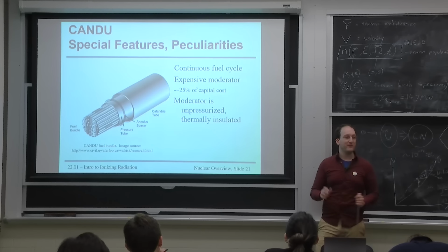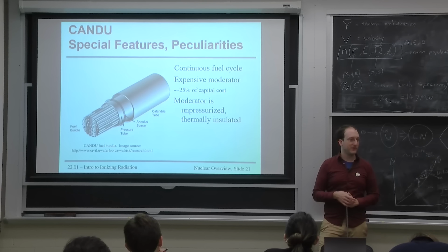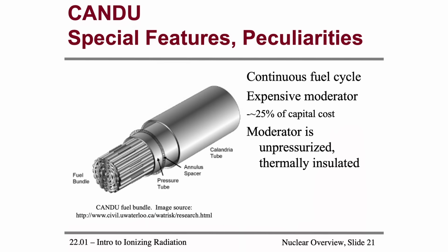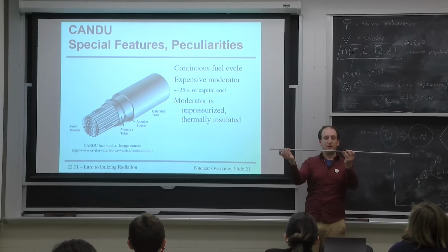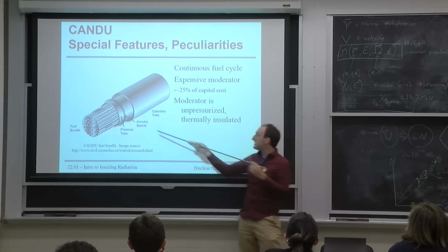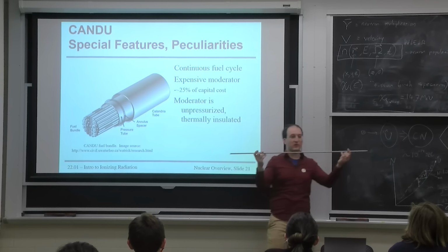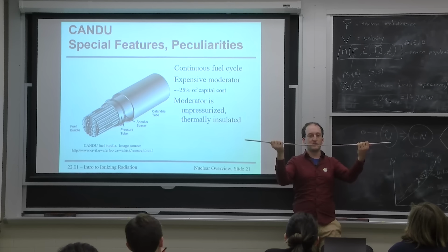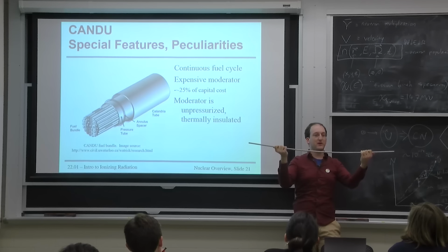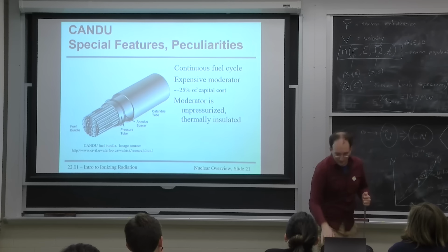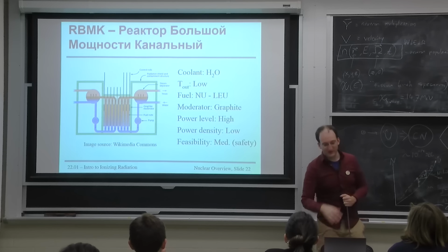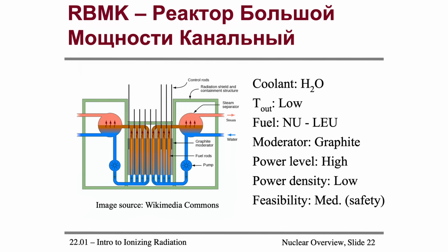And we have a little piece of one of these pressure tubes upstairs if anyone wants to take a look. There are all these sealed fuel bundles inside what they call a calandria tube, just a pressurized tube that's horizontal. The problem with some of these is if these spacers get knocked out of place, which they do all the time, those tubes can start to creep downward and get a little harder to cool or touch the sides and change thermal, and now I'm getting into material science. It's a mess. Then there's the old RBMK, the reactor that caused Chernobyl.